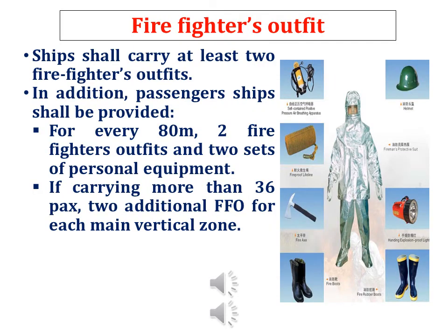Firefighters outfit. Ships shall carry at least 2 firefighters outfits. In addition, passenger ships shall be provided, for every 80 meters, 2 firefighters outfits and 2 sets of personal equipment. If carrying more than 36 passengers, 2 additional firefighters outfits for each main vertical zone.